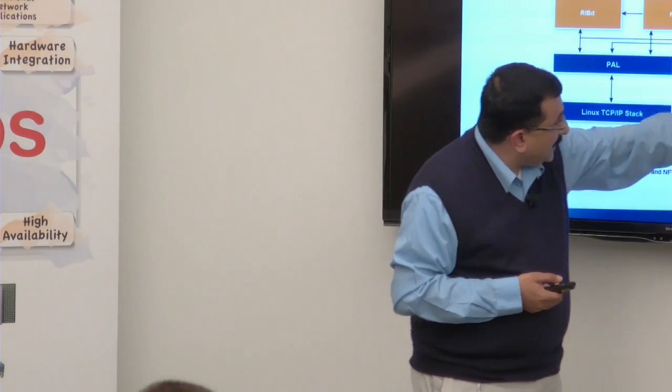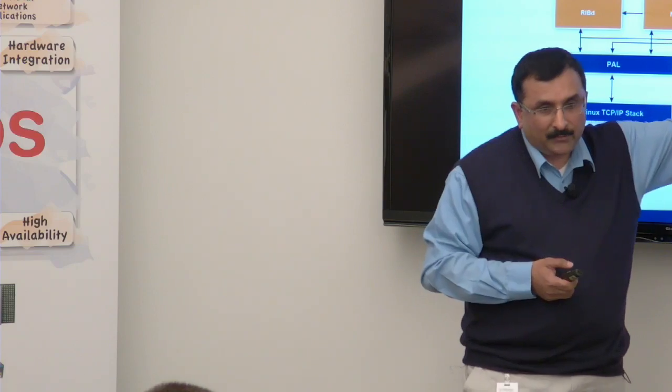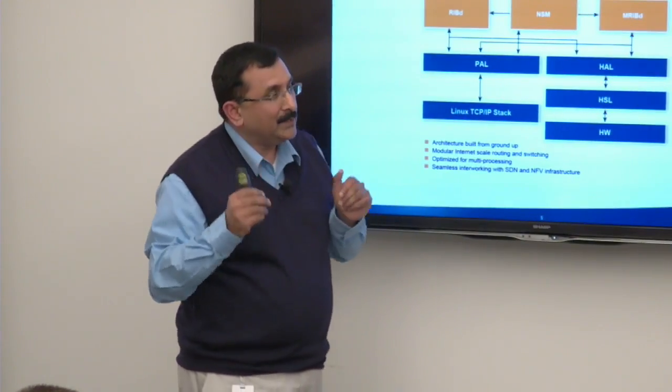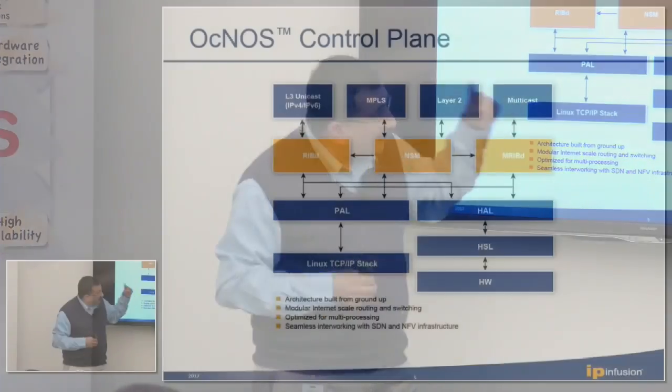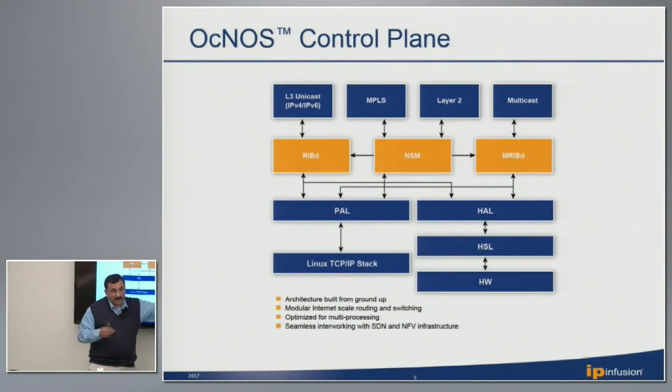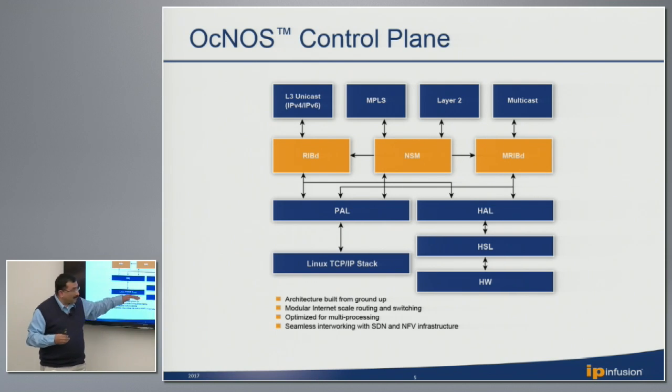Yeah, so what we do is, in addition to what we have here, we have a platform layer. Basically, think of it very similar to a BMC controller, if you're familiar with the BMC piece, right? So what it does is it captures all the underlying hardware states also. So it depends on how good your vendor's hookup is. Like if you get those statistics, we can read those values. We can write a small daemon which reads all the register values and presents you that information, basically. So you can present that telemetry data from the chipset itself, from the chip to whatever tool I have.